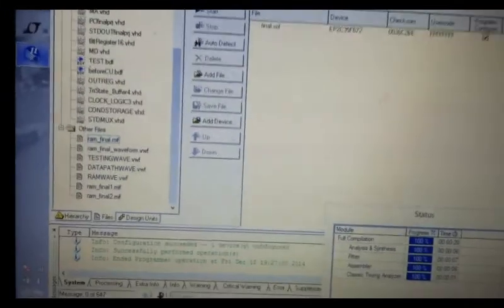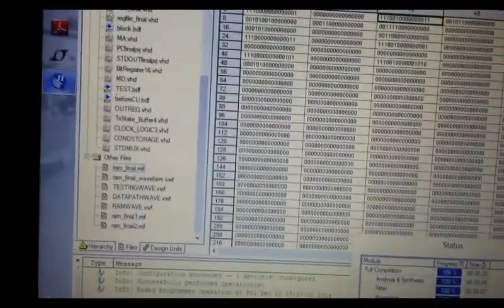And it programs. Okay, and it didn't work because sometimes it just doesn't work the first time. You just gotta clear it a few times. No, oh, there it is. 5. The reason it doesn't work all the time is because this thing is clocked at 50 megahertz, meaning it does 50 million clock cycles per second, and sometimes when you're pressing the button it just doesn't latch properly. So I have one more, and let me just get this set up.